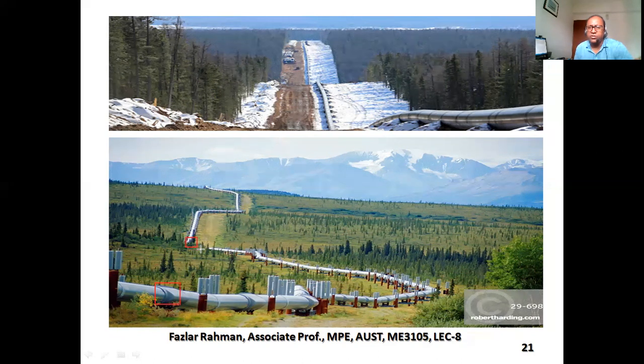If this is point 1 and this is point 2, at this point you have a pressure gauge, so you know P1, you know the velocity, you know Z1, and right there you know the elevation, that means Z2 you know.